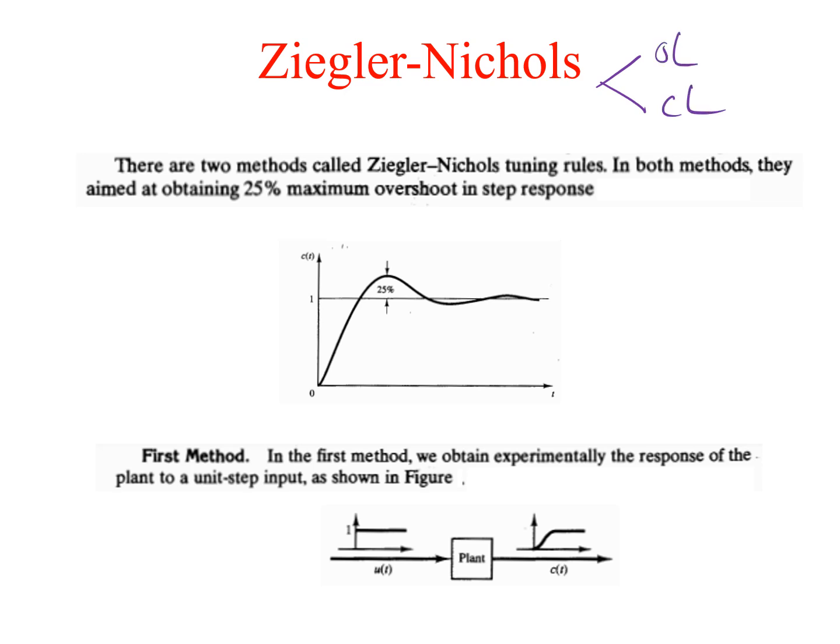So the Ziegler-Nichols method is optimized for 25% offset. That is, this is 25 percentage. Okay, it's 25 percentage in the sense, suppose if this is 1, then 0.25. So this can be added as 0.25. So both the tests are aimed for 25 percentage maximum overshoot.